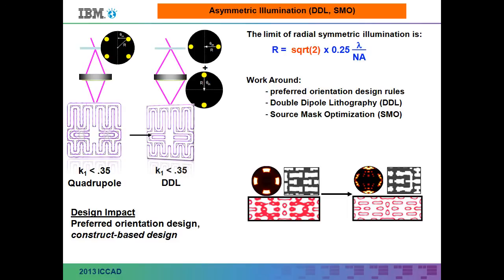It's just like doing 2 exposures on a film camera. Some of you are old enough to remember those things. You put a layer of photoresist onto your wafer, you load your first mask, you expose all the vertical patterns, you don't move the wafer, you keep that there, you load the other mask with all the horizontal patterns, do that exposure, add them together on the wafer, and then continue your processing. And you can recover your resolution that way. But now you're doing 2 exposures.